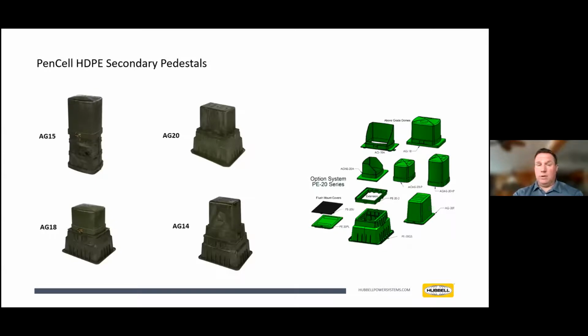These are commonly used in the Midwest, and the reason they are is the material type, the high density polyethylene, is a very rigid type injection foam molding process. The wall thicknesses are commonly anywhere from 1/4 to roughly 3/8 of an inch. Very robust product. You can stand on these things. They're not going to flex, so they perform quite well in the Midwest.